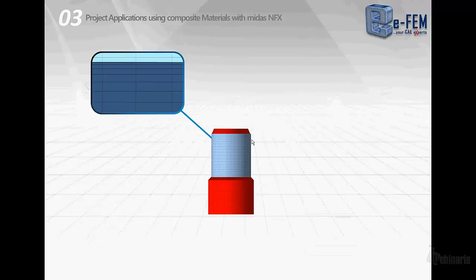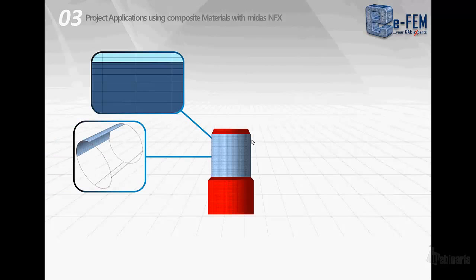The second model, as I told you, is a submodel of the bonded joint, an idealization of the joint. The model has been built manually, starting from a 2D mesh that has been revolved. The model is made of 3D elements, and good attention has been paid to the mesh size and local refinement of the mesh in order to have a good description of stresses.